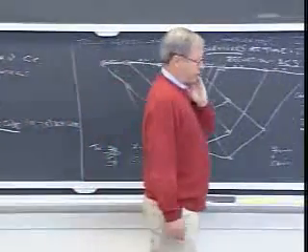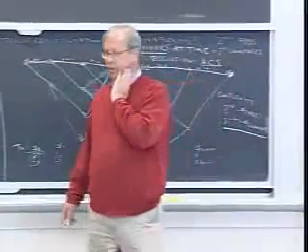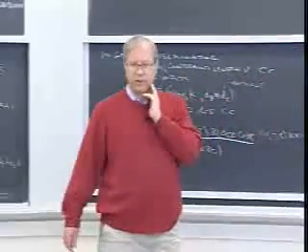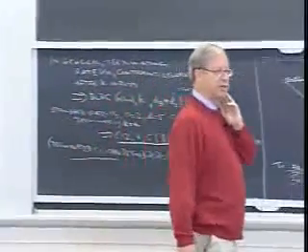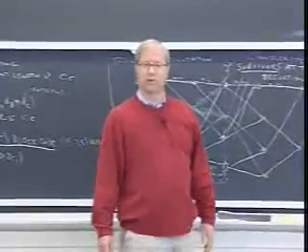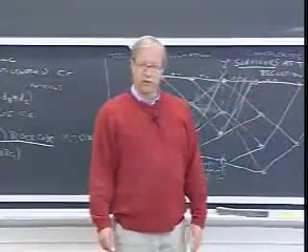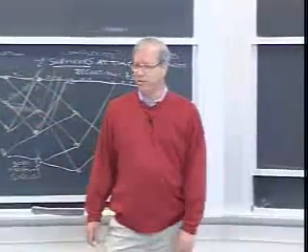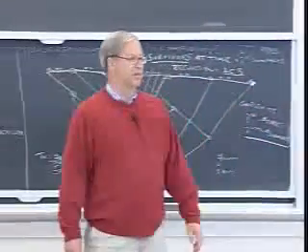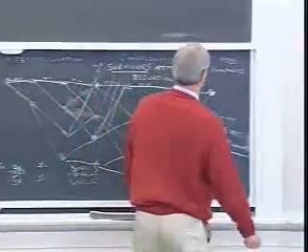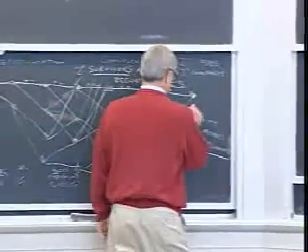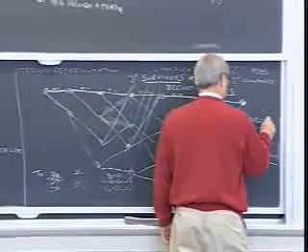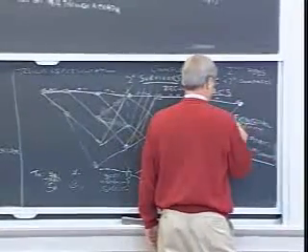The biggest Viterbi algorithm that I'm aware of that has ever been built is the 2 to the 14th state algorithm, the so-called big Viterbi decoder out at JPL that was used for the Galileo space missions. I'm sure nowadays you could practically get it on a chip, and you could maybe do 2 to the 20th states. But this exponential complexity, in computer science terms, is not really what we want.